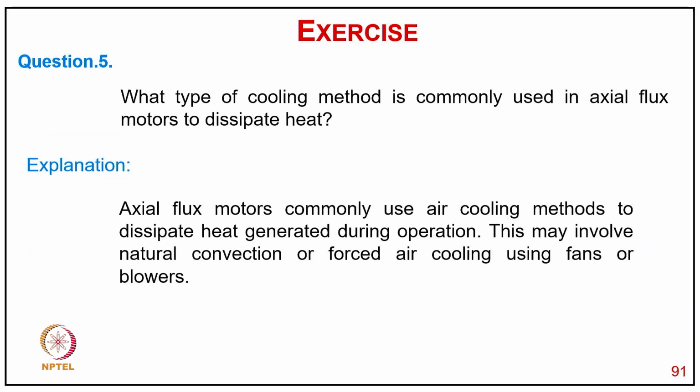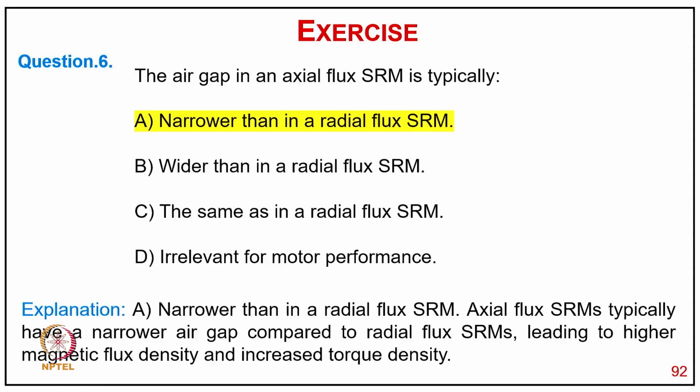Question 5: what type of cooling method is commonly used in axial flux motors to dissipate heat? Axial flux motors commonly use an air cooling method to dissipate heat generated during operation, and this may involve natural cooling or forced cooling, using fans or blowers.